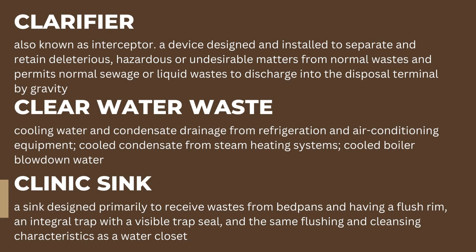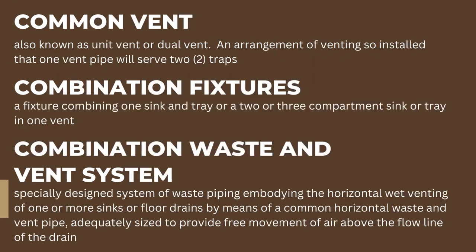Clinic sink: a sink designed primarily to receive wastes from bedpans and having a flush rim, an integral trap with a visible trap seal, and the same flushing and cleansing characteristics as a water closet. Common vent, also known as unit vent or dual vent: an arrangement of venting so installed that one vent pipe will serve two traps. Combination fixtures: a fixture combining one sink and tray or a 2 or 3 compartment sink or tray in one vent.